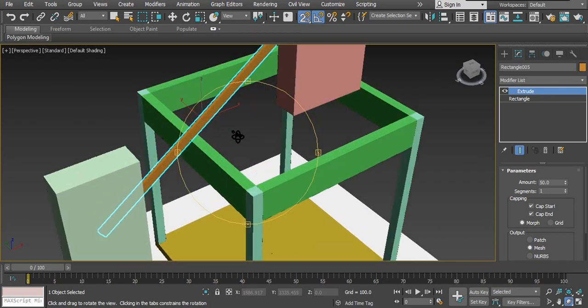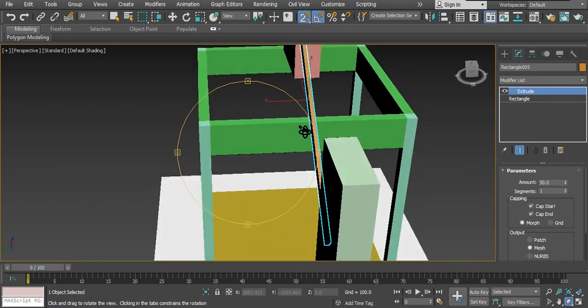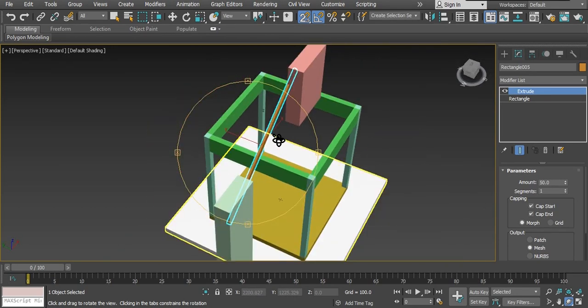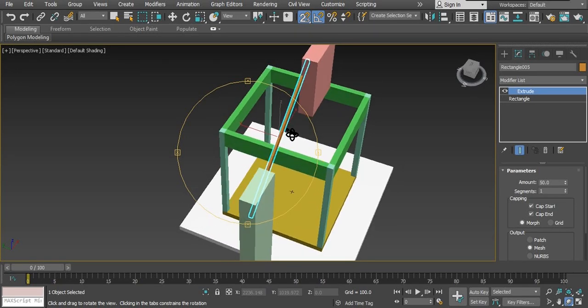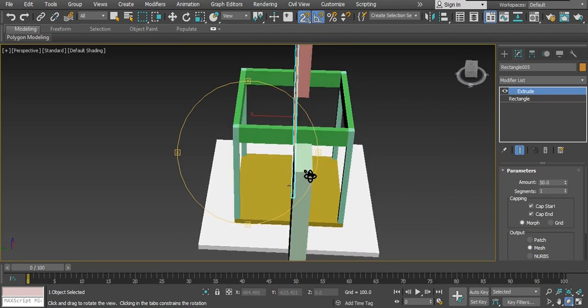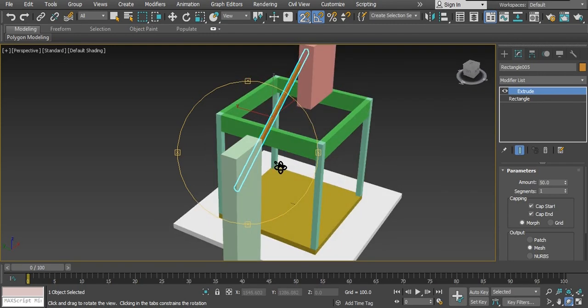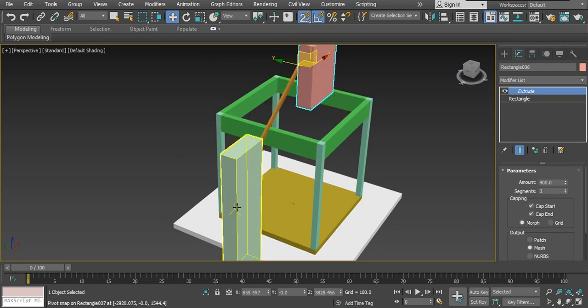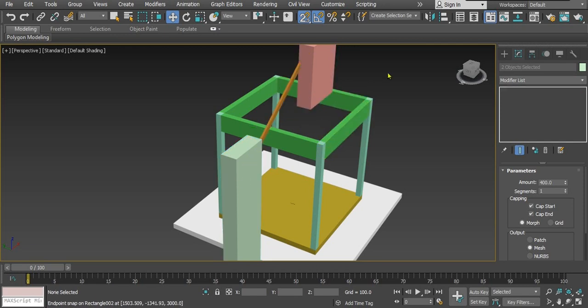Okay, now you have to make sure that these two boxes overlap with the rafter, so that we can subtract these two ends. To do that, you can just select and move. Select one, hold Shift, hold Alt, sorry. Again select one of the objects, then hold Control.